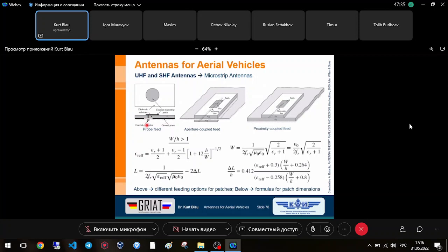Then the inner conductor of the coaxial connector is fed through to the circular microstrip patch element here on the surface. And for instance, here, the inner conductor is soldered on the top. It's not visible here. Normally, you had to make here a point, a dot. You can see then this in practice as a solder point.